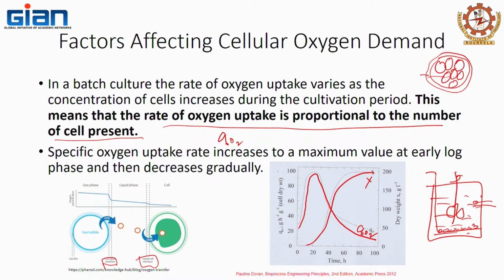Because it is going to break the bubbles into smaller bubbles, diffusion changes, smaller bubbles will have a thinner interface layer. So, your mass transfer is higher. The larger the surface area, the more the catalysis, we call it; the smaller the bubbles, the much better it is.